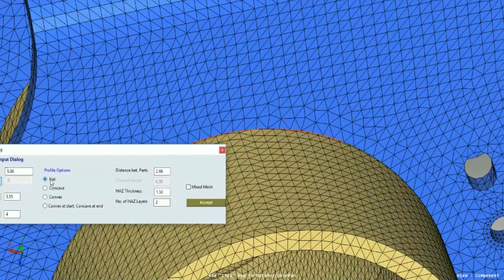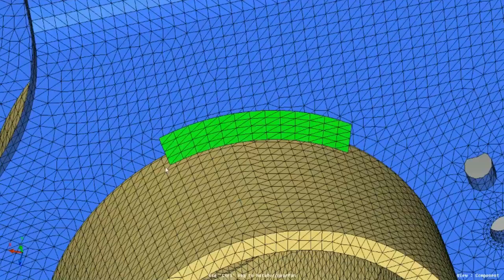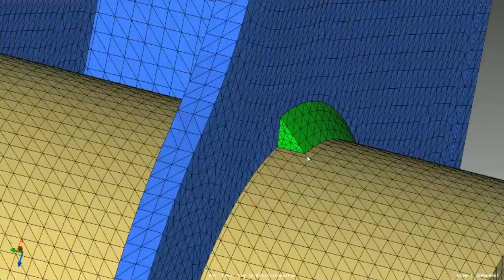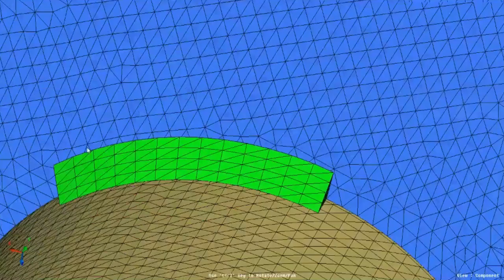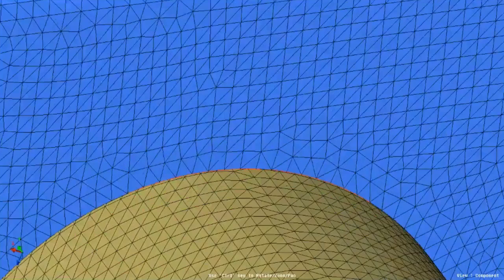For now, I'll just demonstrate the flat weld. So the weld type is flat, and in the align type we can use merge nodes, coincide nodes, or non-coincide with contact. If we create merge nodes and preview the weldment, the weldment has been created, and since I selected the weld type as flat, you see the profile of the weld is flat, and also it's a 3D tetra weld.